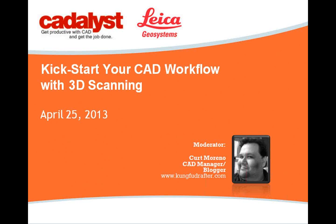Wow. And so Cyclone is able to take that mass of individual points that looks like a cloud, like a digital fog, and derive line work from that. Yeah, that's where a little bit of the magic comes in, and where your point processing software is particularly important. Not only when you get the data, but how to put it together in the same coordinate system. And yes, you're right. How to get your line work, your DTM or TINs, or your block primitives like street furniture, or for the plant industry, pipes and valves and whatnot.